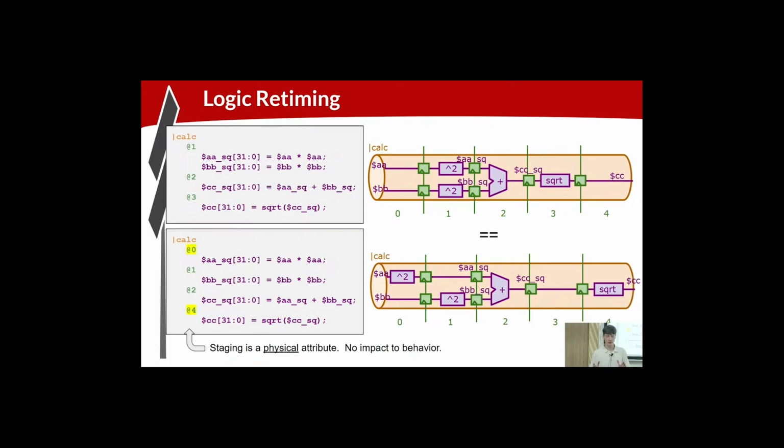Yeah, so the flip-flops are going to exist wherever they're needed, right? The existence of these flip-flops, the existence of stage 0, just depends on the assignment of A and B. Where are their assignments? Right, so the pipelines are conceptually infinite. All signals exist anywhere they're needed. So me showing flip-flops implies that I've implemented this. The implementation and the existence of those flip-flops just depends on the surrounding logic.